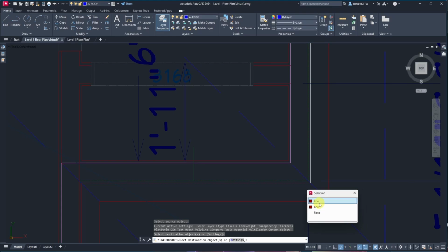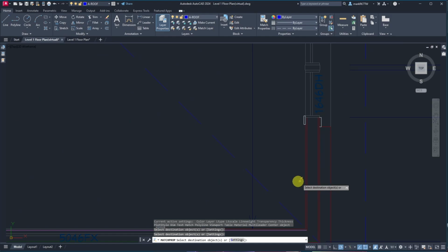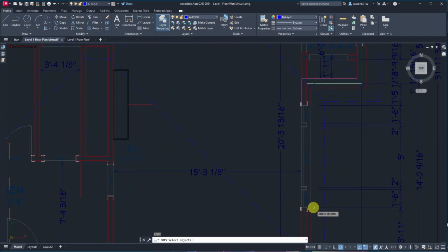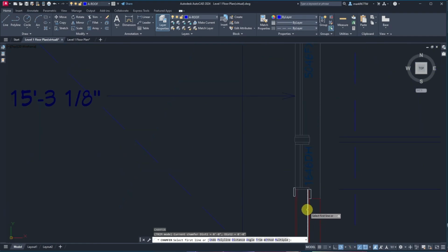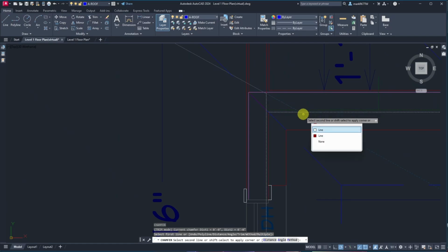And if the first one works, you can just keep going. You don't have to tell it what you want. If the first one's it, let's say it's this, and oh, there's only one line there. So now it's just a matter of chamfering that. So CH, my chamfer distance is set to nothing so that it ends up at a point.